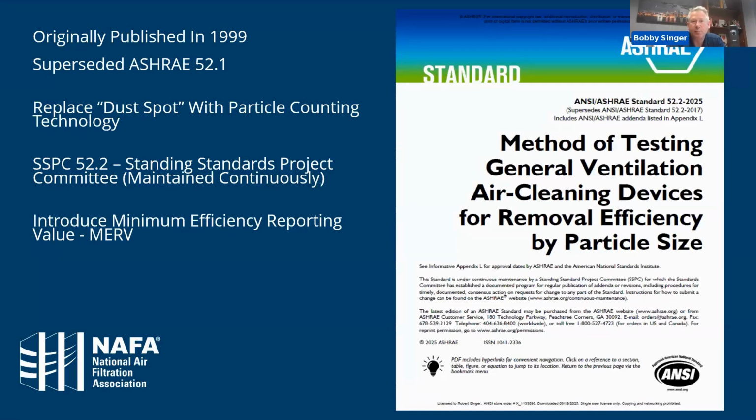utilizing the old dust spot technology, which is what this method 52.2 replaced with the particle counting technology. The old dust spot was basically a filter paper installed upstream and downstream of a test filter, measure the opacity through each of those papers, and the difference in that opacity would be the efficiency.